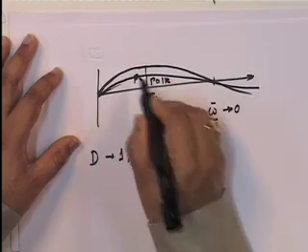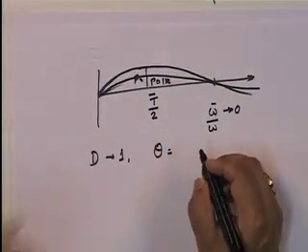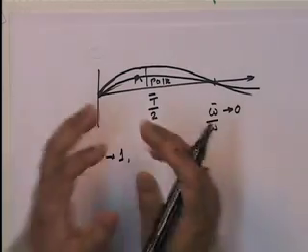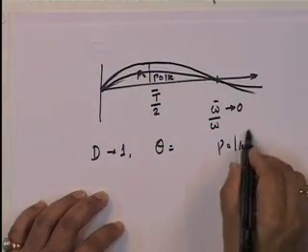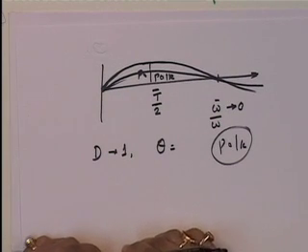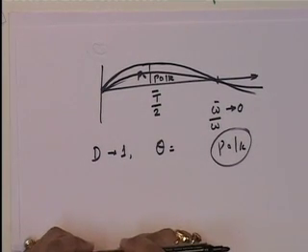We are actually plotting it in two different scales, but the point that I am trying to make is that for a slowly varying load, as far as the structure is concerned, it is being subjected to a static load. So, if the excitation frequency is very low compared to the natural frequency of the structure, you can, for all practical purposes, not have to do any dynamic analysis, because what's the peak response? P naught upon K. You might as well do a static analysis for the load amplitude P naught.